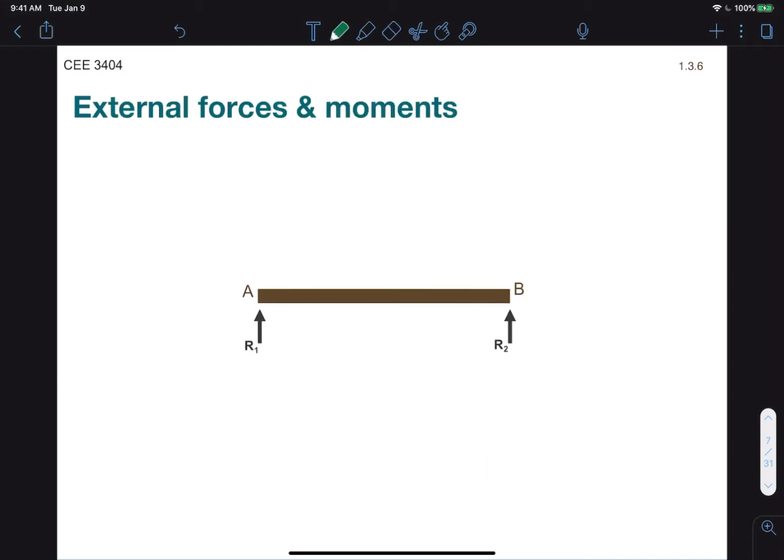There are 2 ways to think about forces, as external or internal. But any way you slice it, these conditions for static equilibrium need to be met. So let's think about external forces first, then we'll move into internal forces. Let's take a free body diagram for an ideal weightless beam, AB, which is supported vertically at both ends. The supports generate what we call reaction forces. And these are very generally labeled using the variable r.